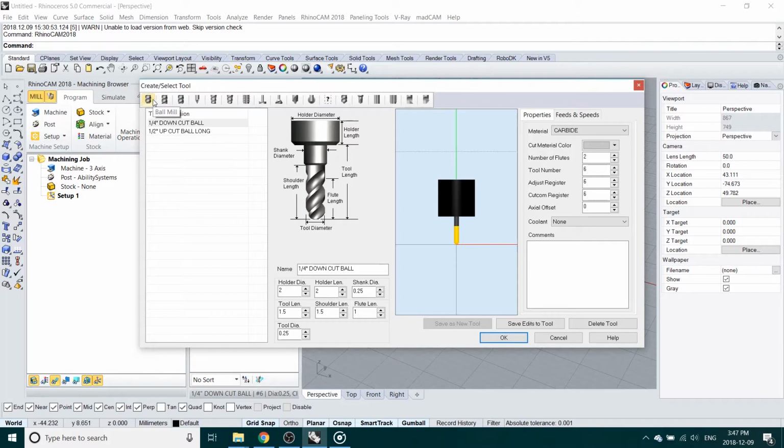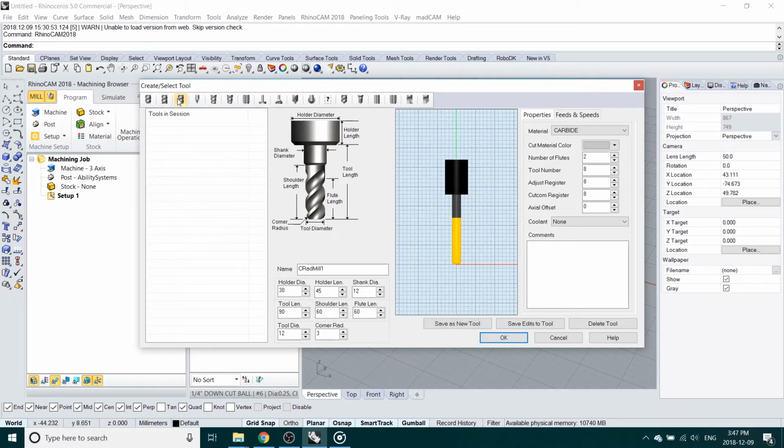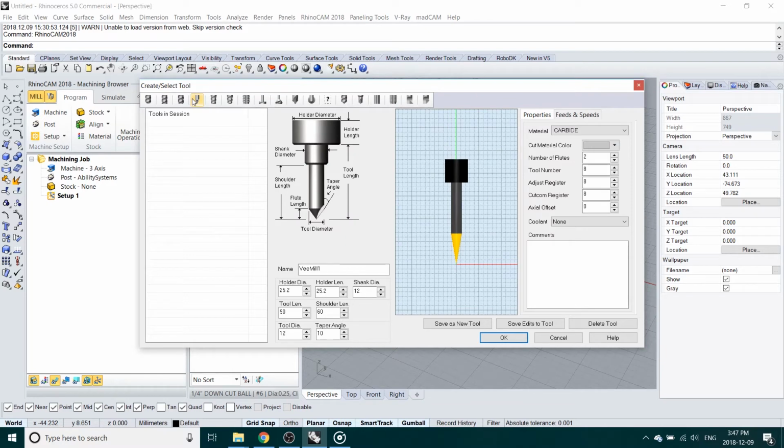The ball mill is a bit that has a rounded edge at the tip. Its intention is for the removing of material in contoured conditions, especially in the 3 axes. Flat mill is a bit that is ideal for removing material in the 2 axis direction. This bit allows for tight corner conditions when removing material. The corner radius mill is similar to the flat mill, except that the corners of the flat portion of the tip are filleted. The V-mill can be utilized for engraving into the material.